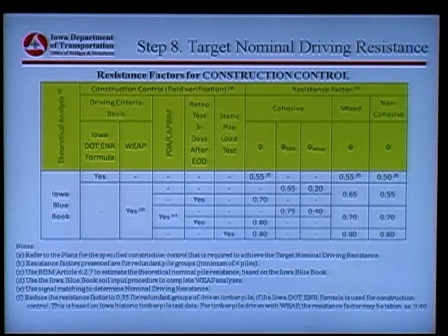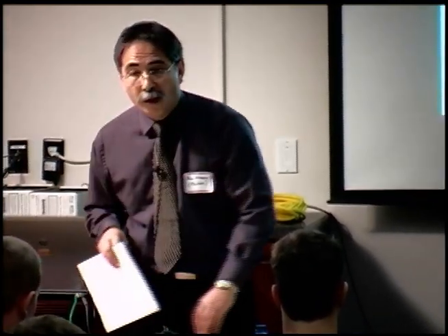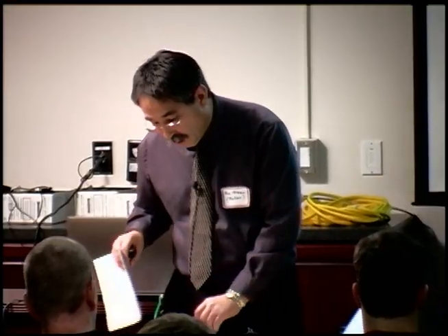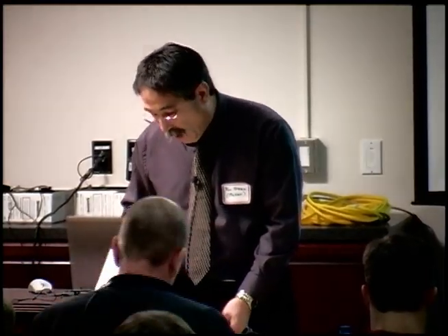Now that we've gotten out of the design, the only other thing to remind you of is, when we got the resistance factors, you have to remember to go to the correct chart. The resistance factors are on page 141 in volume 4. You'll notice there are 2 tables, C1 and C2. C1, at the top of the page, is for piling in compression. C2 is for if we have tension piles. So that's the one we use for design and contract length. That's where we were a few minutes ago. That's the first half of the puzzle.